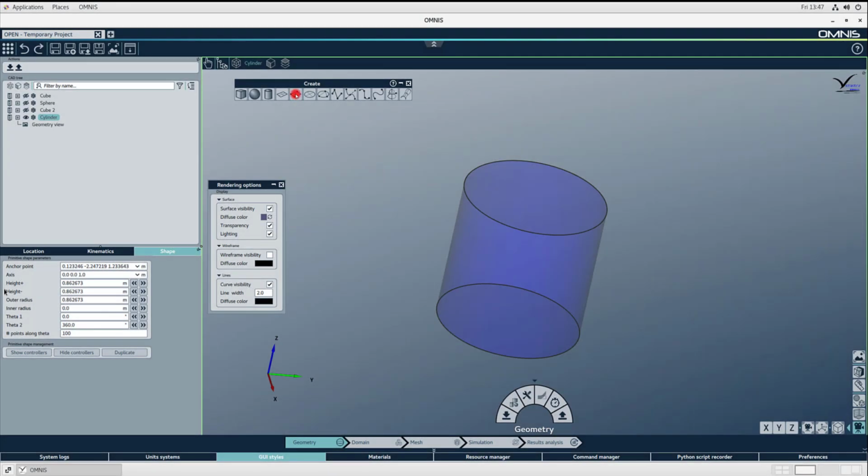The second option creates a plane from 3 points that you select in the Graphics area. The distance from the first point to the second one defines the length of the primitive. The perpendicular distance from the second point to the third point defines the width of the plane.